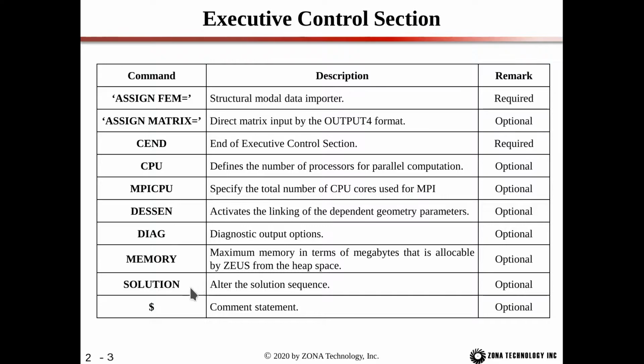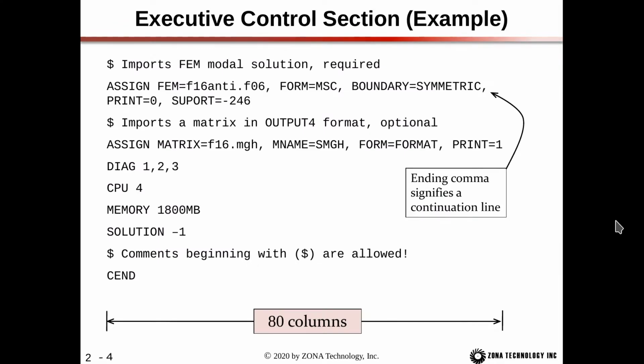The solution command, which can be abbreviated as SOL, alters the solution sequence. And then finally, the $, as we've seen, is the comment statement. So this is an example. We have the assign FEM command.